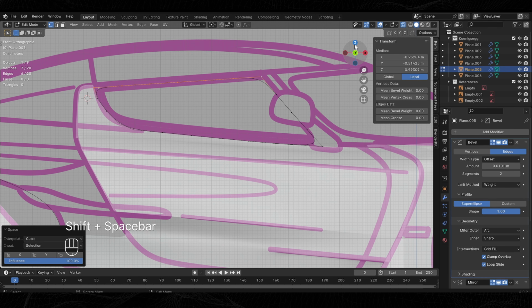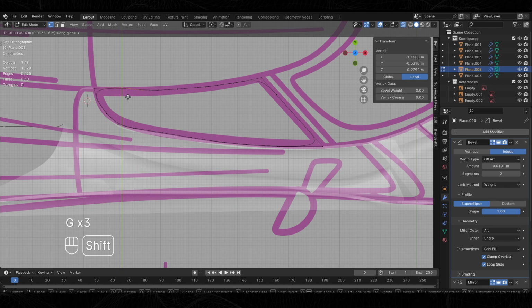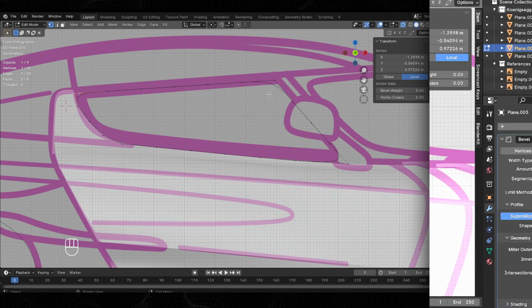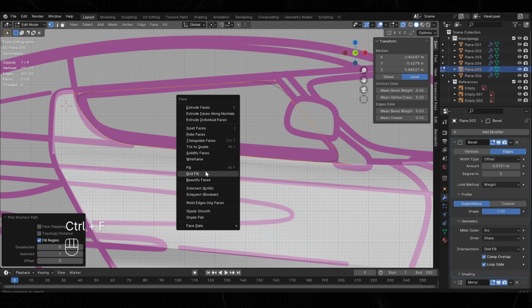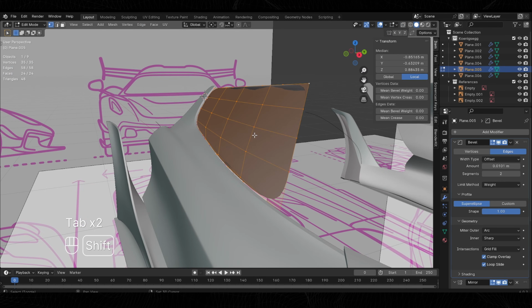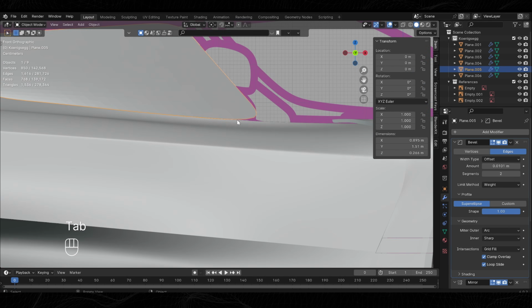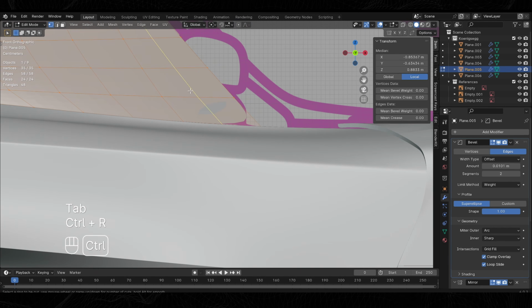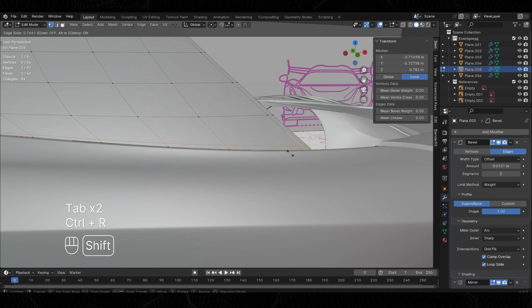After that, you can go into side view. Adjust these vertices here, then fill everything using grid fill. Here use Shift+N to recalculate the normals. To make this window maintain the correct shape, I also added some reinforcing loop cuts on these 3 sides.